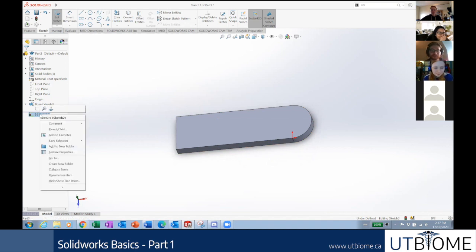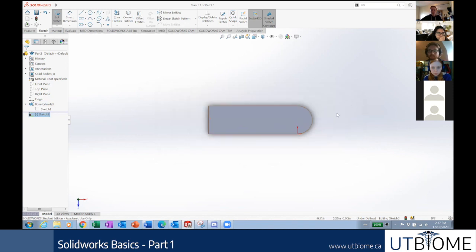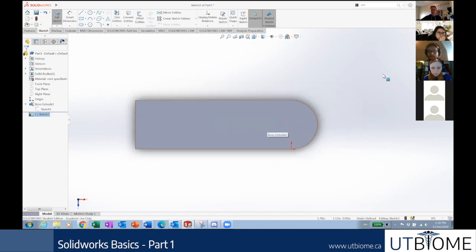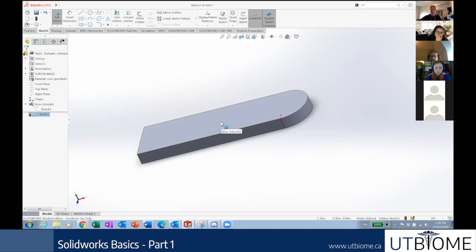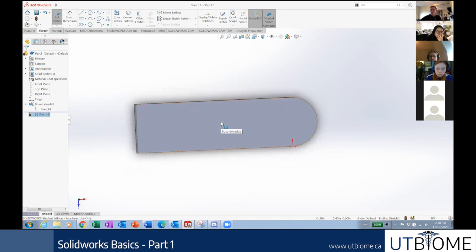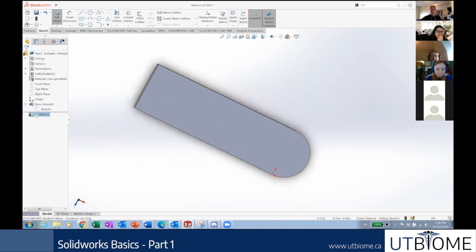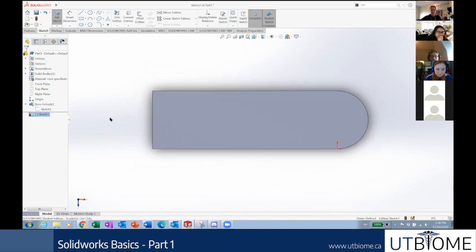I'm just going to right click on sketch 2, then left click on normal to. That's going to bring us perfectly facing this so that we can just sketch and there are no weird angles. We've got the perfect perspective here. I'm going to be doing that a lot. Every time I start a sketch and things are slightly slanted like this, I'm not going to manually try to get it close, holding control or maybe Alt will do the trick. No, we're just going to go straight to sketch, right click, normal to, boom.